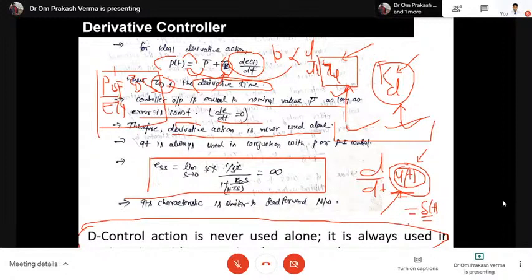So as you apply the error like this, after the control action it gives a very sudden shock to the system. To avoid such a sudden shock, which may harm your system or affect it very poorly, we avoid this type of input. Therefore the derivative controller is never used with it, because you can't change the signal, the step, from such a type of step change.